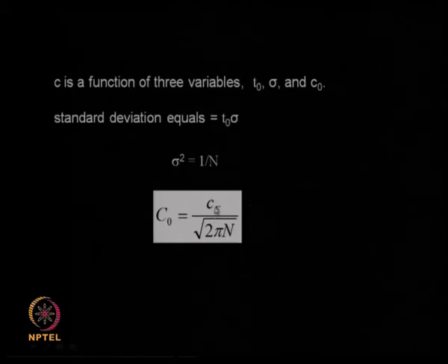So again, if I know Cf, that is the feed concentration, and if I know the number of theoretical stages, I can tell what will be the maximum concentration of that particular peak that is going to elute out. So you see these equations are very useful for doing plenty of calculations. We are going to look at it as time progresses.